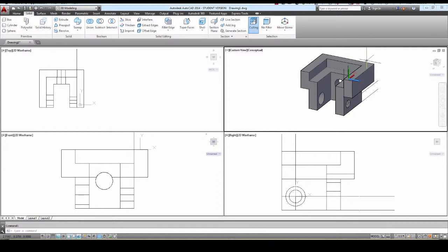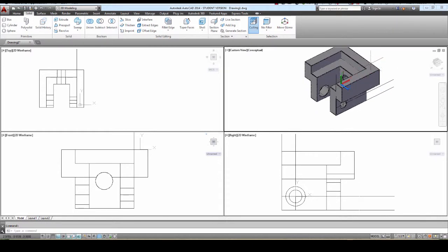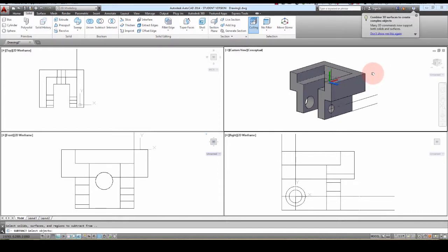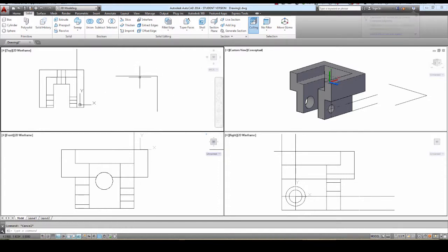So say for instance I wanted to put a fillet on this corner up here. Okay, I want kind of a rounded radius up here. It works a little bit different than fillet does with regular fillet. When you have two lines going like this and I want to put a radius in there, I use the fillet command and I give it a radius of say 2, right? And I pick this first line here, pick this second line here, and it puts in that fillet.